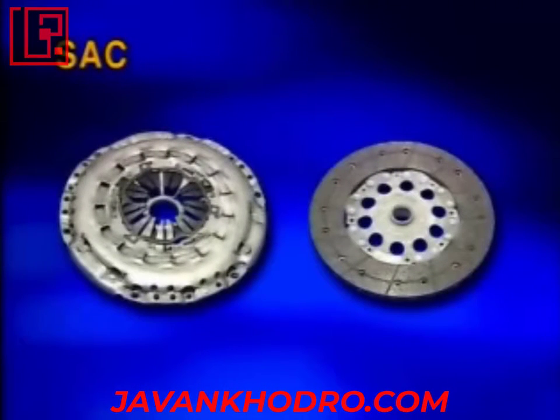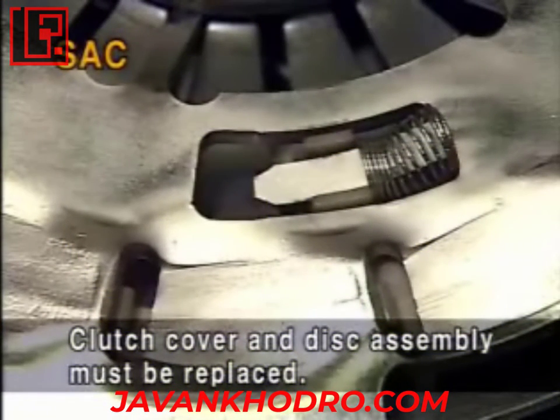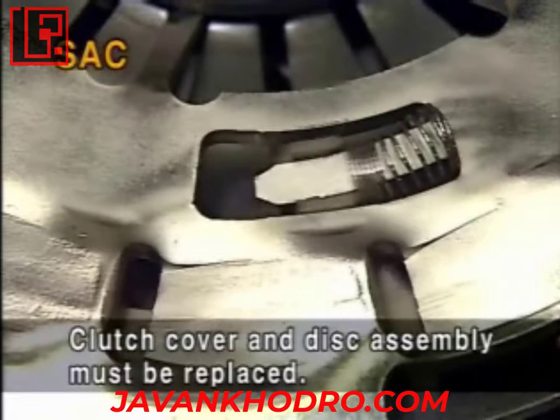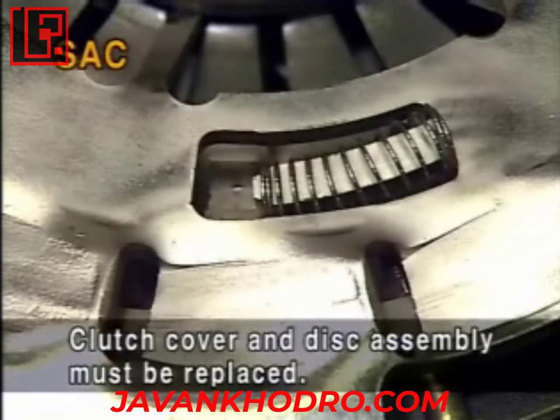When replacing the clutch disc, the clutch cover and the disc should be replaced at the same time. The reason is that the clutch cover is adjusted to the clutch disc wearing out. If the new disc is installed with the old disc cover, the cutting out of the driving force has a problem.